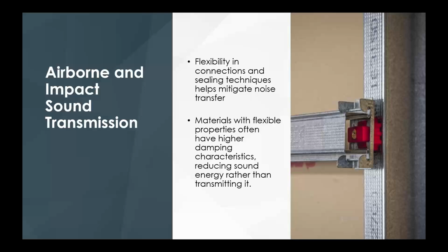Going back to that flexibility. What we have here is a sound gasket. You see this red gasket, and then you're going to have a hat channel that's going to attach into it, and that's going to reduce the vibration. So you can see how that rubber gasket is going to work there. It's going to reduce sound vibrations, and it's going to improve your STC ratings.